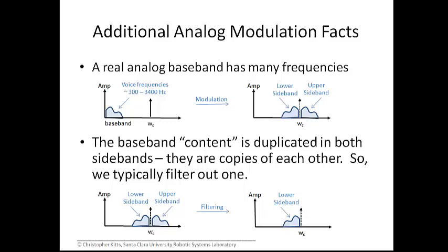And so, for example, you can see in the upper left-hand plot there, when we record voice, we see that the frequency content of voice is sort of below 3,500 hertz. Okay, it's a couple hundred hertz to 3,500 hertz or so, and it's a whole range of use of that little chunk of spectrum right in there. So when we modulate it, every single one of those sort of gets reflected. Okay, it gets modulated and generates its own difference wave, and you can see what we get is sort of a reflected version of that chunk of spectrum centered around the carrier wave.